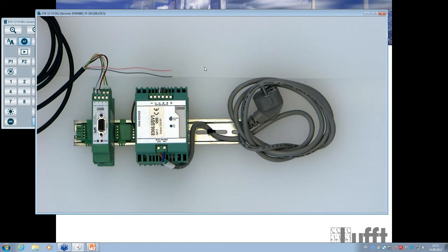It's really easy because you only need 2 wires, and you don't need to check the polarity. You can connect them directly to the PLC. The only thing is that you need to configure your PLC, but that's not our work, that's your work, because you can configure nothing on the WTB100 since it's a standard impulse output.